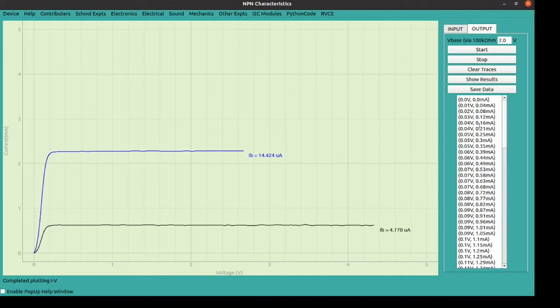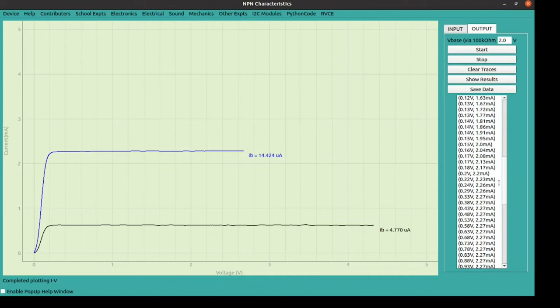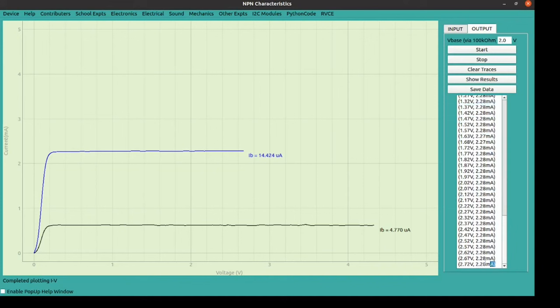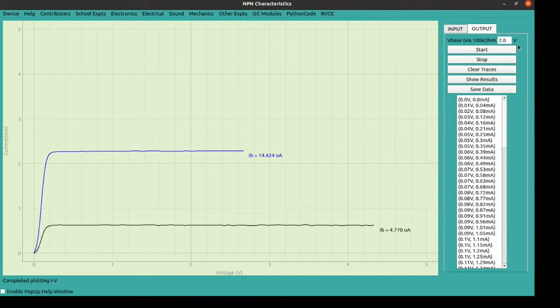We can see that in the table, in the right side column, wherever the voltage is constant, that is IC2. So these two values, IB1 and IB2 and the corresponding IC1 and IC2, help us to find the current gain. To plot the graph manually from this table, wherever repetitive values are there, only the first reading has to be noted down.